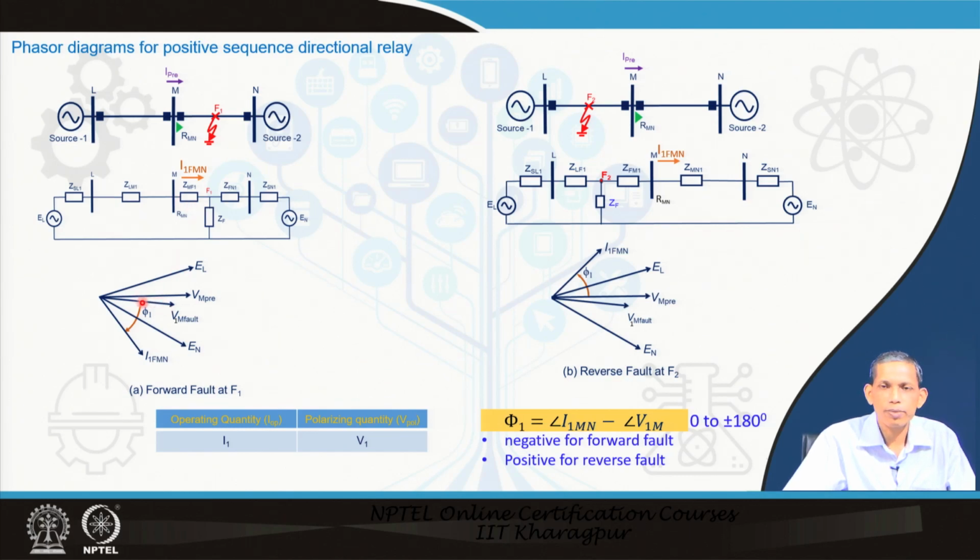So, therefore, at that time the corresponding voltage will be close to the pre-fault voltage and somewhat lower depending upon the dip in the voltage. So, this leads to this corresponding situation like this. Note that the corresponding fault current will lag the corresponding VM pre or VM fault. So, therefore, it is lagging, and from this perspective we see that this current will be lagging in this path.